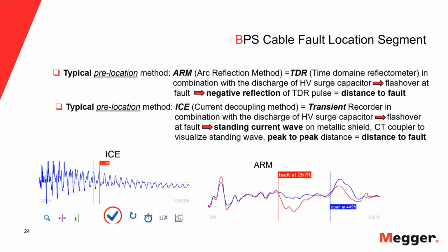So we are basically getting a signal on the neutral, which forms a standing wave between the fault location and the capacitor inside our unit. And on the left-hand side, you can see this curve. It looks like a sinusoidal curve, but it has repeated peaks in it, and the peaks all have the same distance, and the forward distance equals the peak distance.